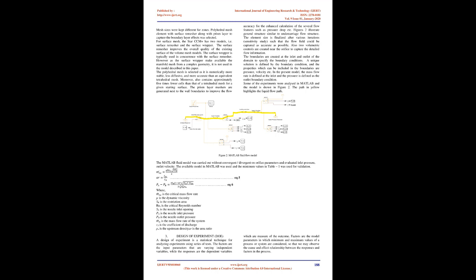The coefficient of discharge, which is a very important parameter for the characterization, was given by Benjamin [2] as Cd = Q/(A√(2ΔP/ρ)), where A equals net orifice area and Q equals volumetric rate of discharge. Multivariate optimization generally implies 2 steps: A.